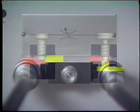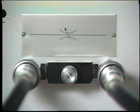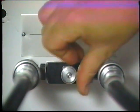As a flow control valve is opened, the flow rate through it increases. This, in turn, increases the flow rate into an actuator and increases its velocity. Closing down the orifice reduces the flow rate and reduces the actuator's velocity.